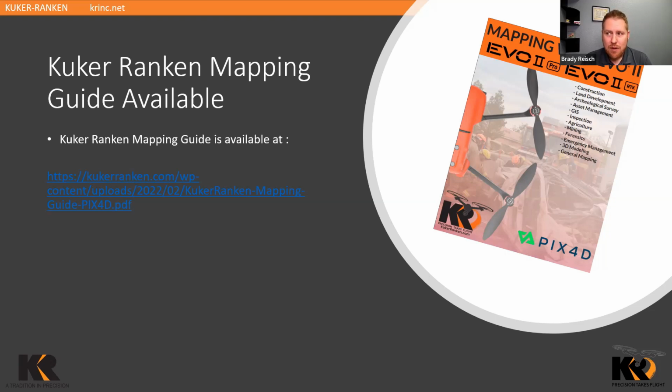One last thing I will bring up with the drones is some of the drones have the mapping software, such as the Evo 2 system from Autel. However, the Autel Lite and the Autel Nano systems, although they've got great cameras, don't have the same software on the back end, which means you would have to manually move the aircraft around and try to adjust your overlap and get everything correct before you can process your map together.